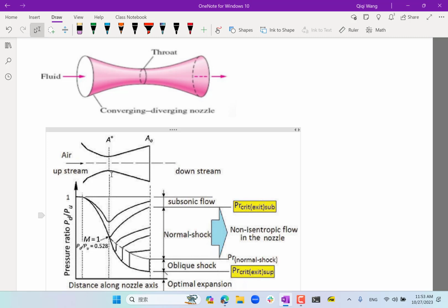Again, the higher Mach number you have, the lower the pressure you have. That's something we looked at in the differential analysis. That is why, as long as the whole throat is subsonic, we have this qualitative relationship that the pressure is a function of the area.